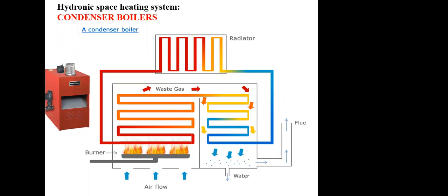There is no risk because nobody will stay in the basement for a long time. But if you have a boiler in your kitchen, make sure that you don't get this air inlet from indoors. So you get it from outdoors. You have the combustion, and if there's an air leak, the air is there.